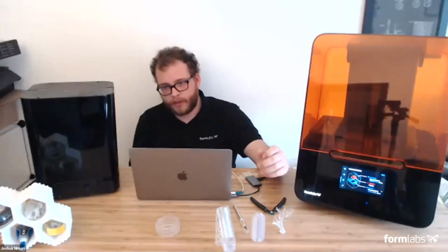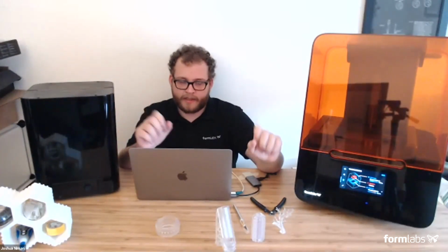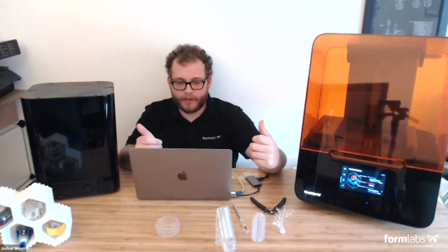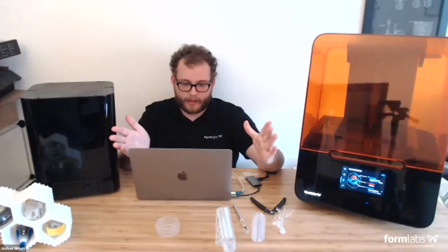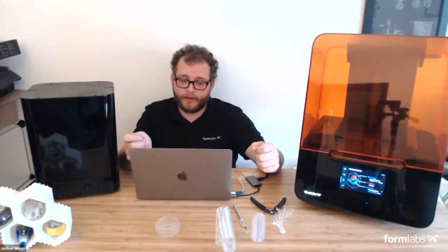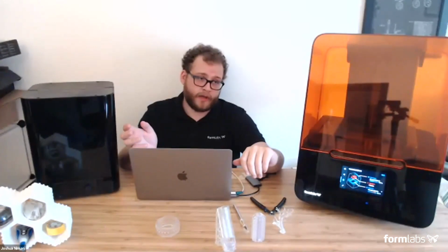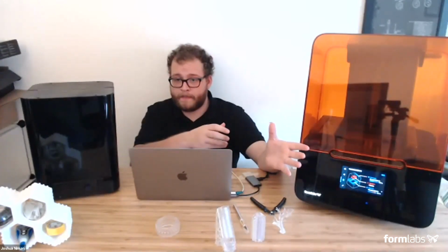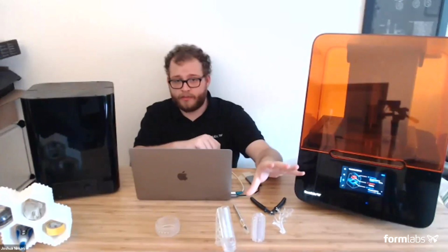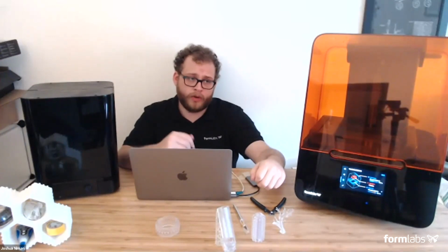I think the only thing I can think of is, can you explain what a Shore durometer is, what that measurement means? Yeah, absolutely. So basically, there are multiple scales for hardness. That Shore A scale is generally used for elastomers, for softer materials. So lower is a softer material on that scale. So Elastic is a significantly softer material than our flexible material. You can think of Elastic as more silicone-like, pretty soft, pretty pliable. Flexible is more like a TPU or a hard rubber, like the sole of a lugged boot or a tire or something like that.